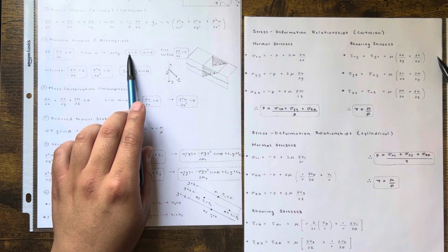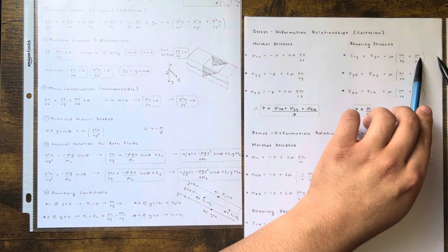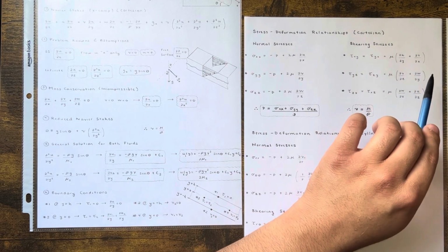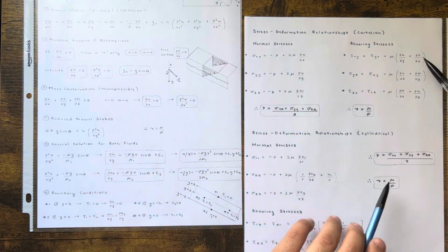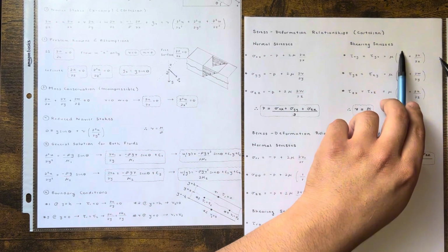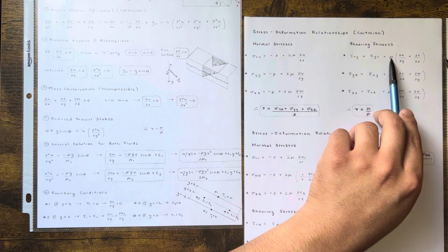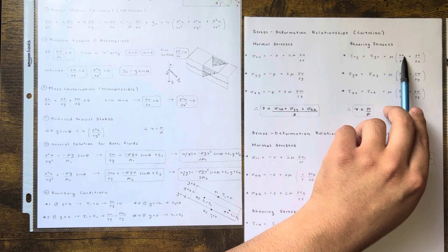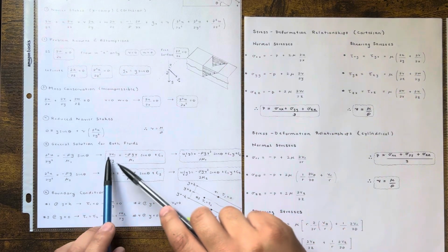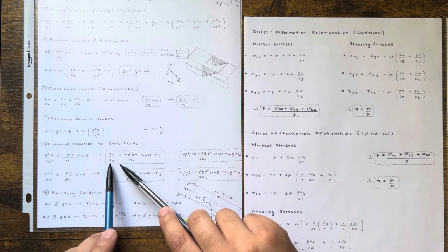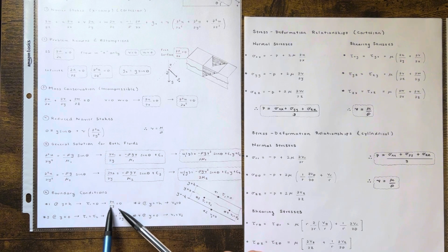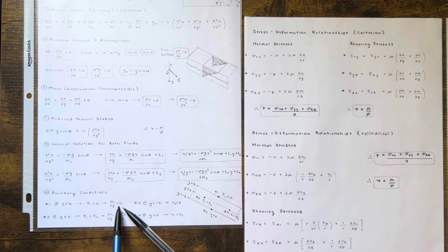So partial v, partial x, the derivative with respect to x of 0, is just 0, so this goes away. You're left with this term, partial u, partial y, of fluid 1, so mu1 times partial u1, partial y. So tau 1 is equal to 0 means partial u over partial y is equal to 0.